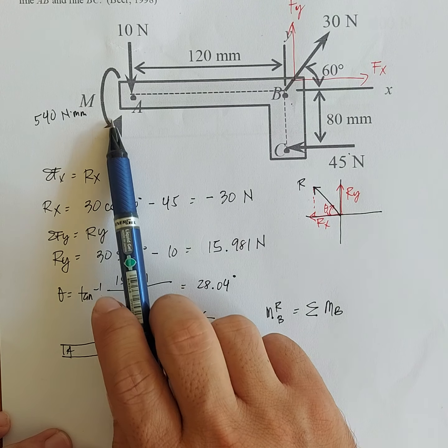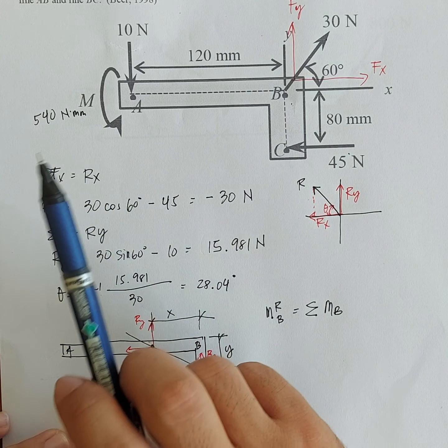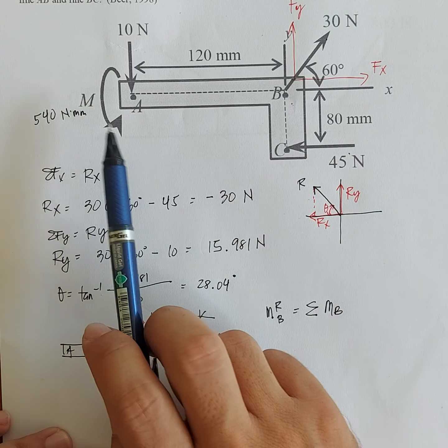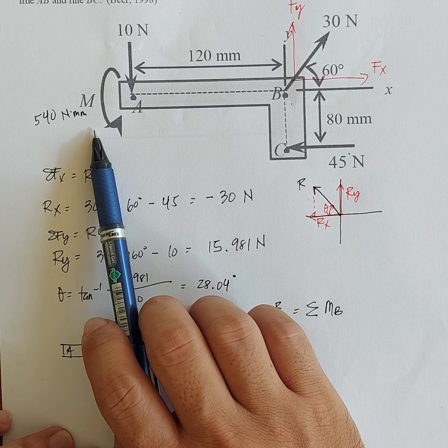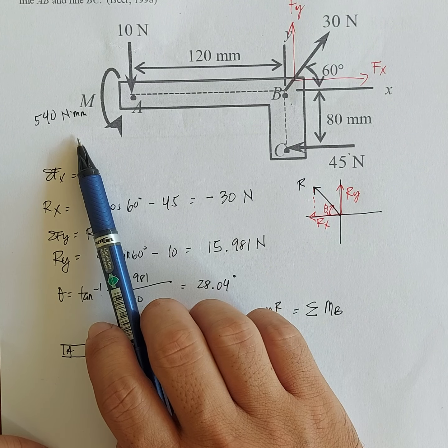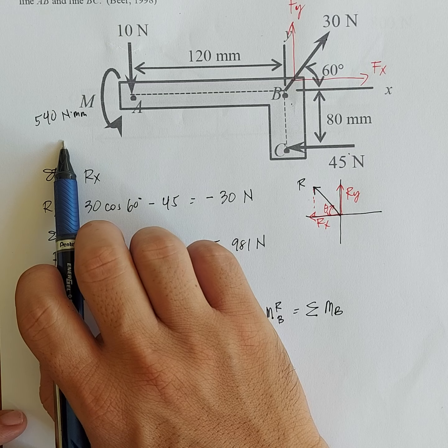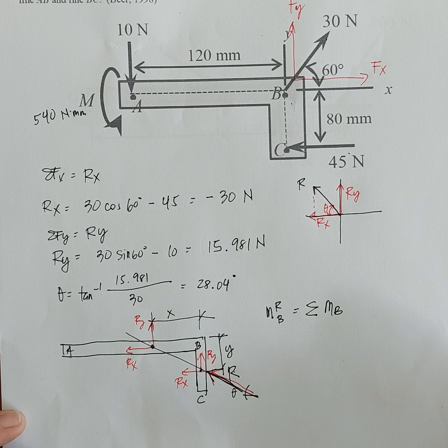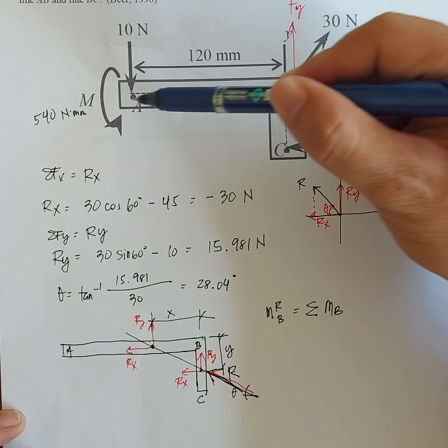So, take note, we did not include this dun sa pag-solve ng resultant force, no? Kasi hindi siya force, it's a moment, it's a couple, moment of a couple. Okay? So, ito, pero isasalin natin siya, of course, when we solve for the resultant moment or when we summate moments at a certain point, we have to include this in our equation. Okay? So, ano yung mga may moments? Of course, yung 540 Newton millimeter na couple, which is counterclockwise. So, negative siya. No? Okay. So, negative.